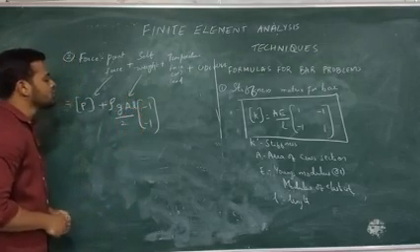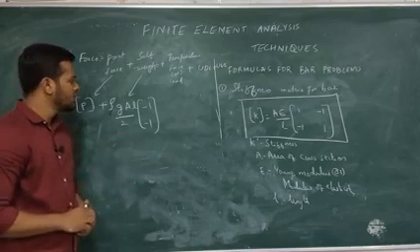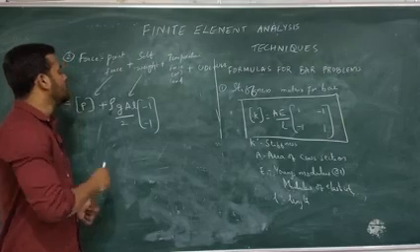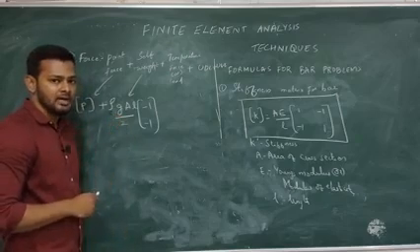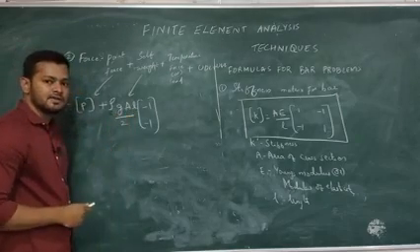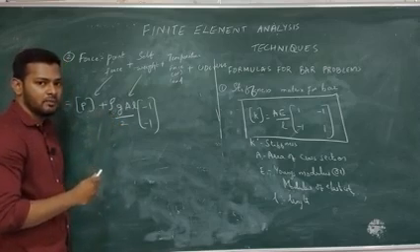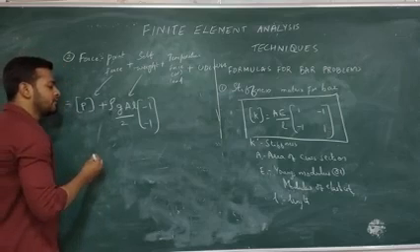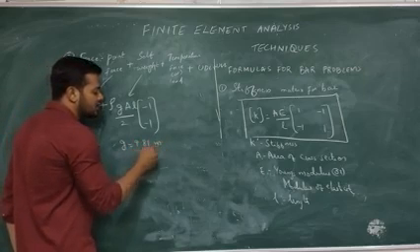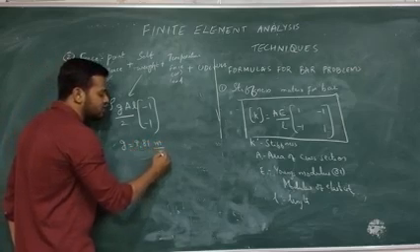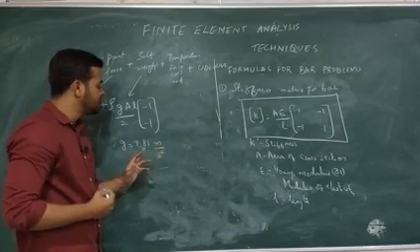One thing many students make a mistake on in the final exam is when they are substituting rho, area in terms of millimeters, millimeter square, length in terms of millimeters, but they substitute g as 9.81, but g is 9.81 meters per second square. So there you should be very careful. While substituting this g value, it's not just a 9.81 constant value, you have units also. So that small g value is 9.81 meter per second square.